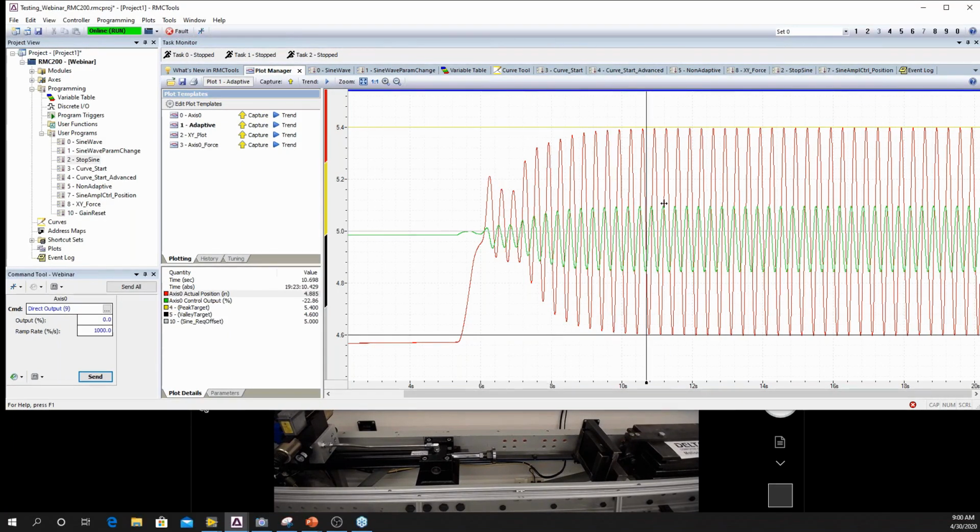So we're actually able to do this with a fairly small amount of tuning. This has been such a great program to have as a thing in our back pockets. If you're really trying to do something with very high frequency or higher amplitude, and for one reason or another your system just can't keep up, a lot of times we can solve this with our adaptive amplitude. We're able to make sure that each cycle is right on, and we're able to do this for as many cycles as you like.